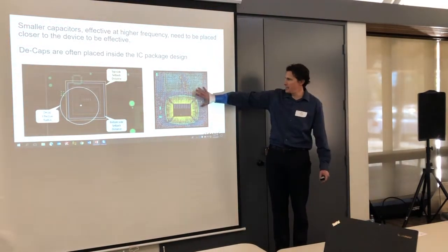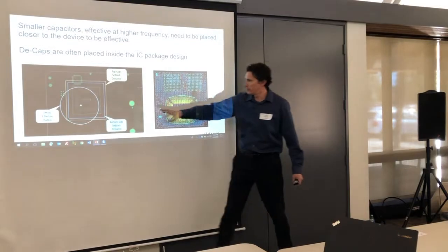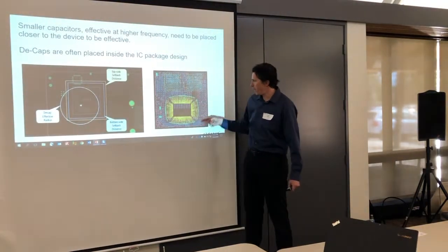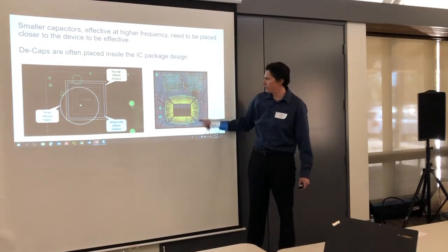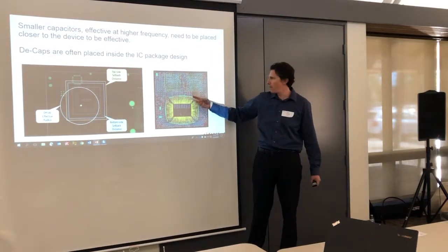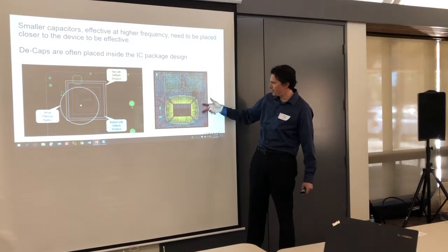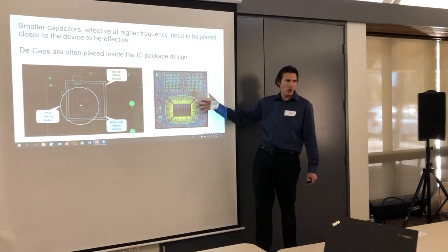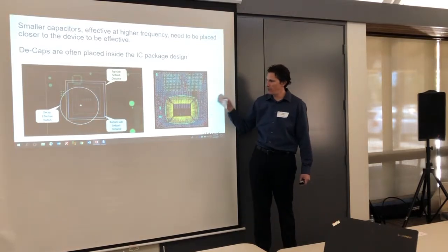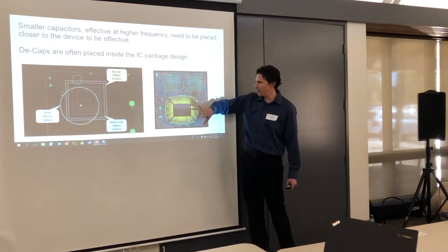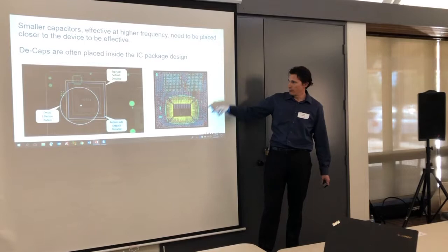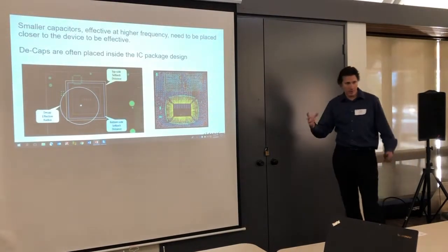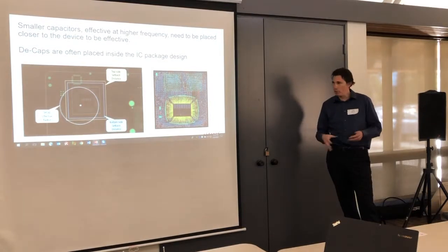You're seeing this is inside a BGA package, so this is what you see on the PCB. This is inside the package, and you're going to start to see capacitors. In fact, this has been happening for quite a number of years now. Capacitors inside the package: these are decoupling capacitors for that IC, because they just have to get that close. Otherwise, there's no way that they can effectively release their charge to get there in time to affect the switching of that. But anything that's been put on your board, most likely the hardware designer has realized that they can still have value on the board.